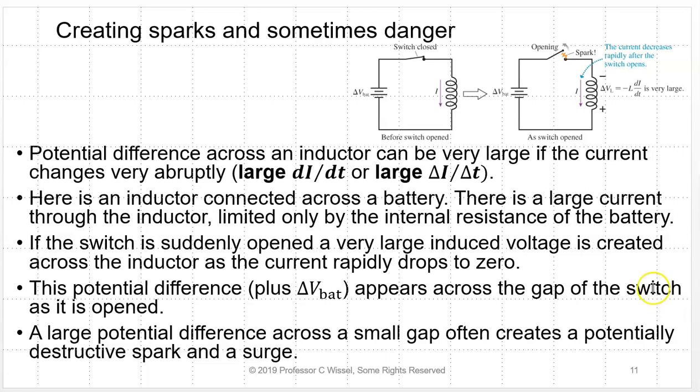Now, you should never, ever plug things like refrigerators or pumps or compressors, or anything that has a motor in it, on the same circuit with something sensitive like a computer, your television, your cell phone charger, your Wi-Fi adapter.